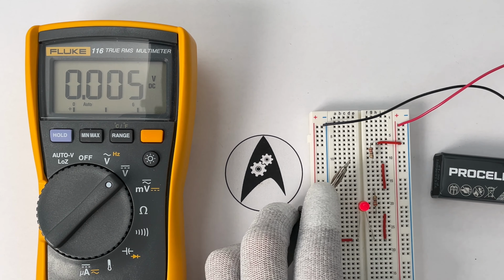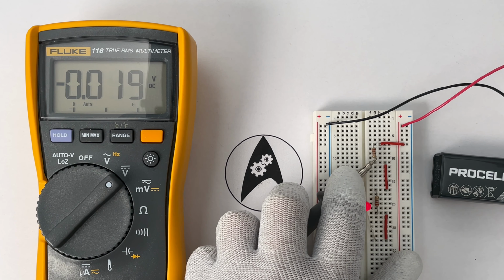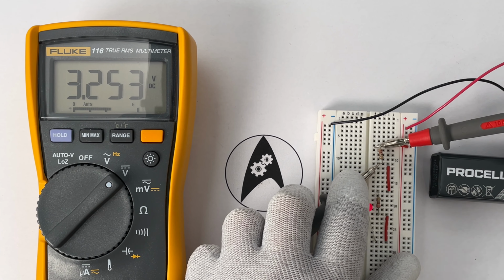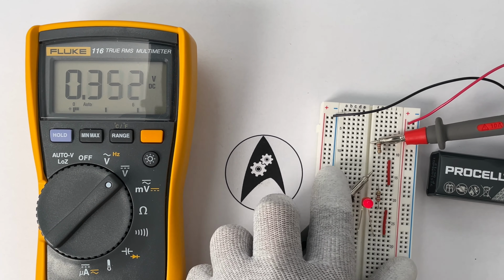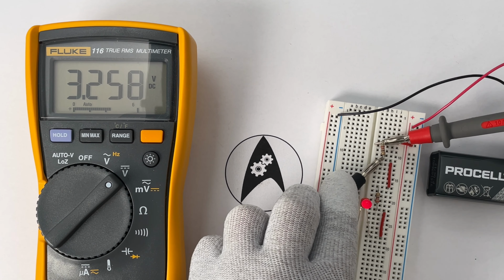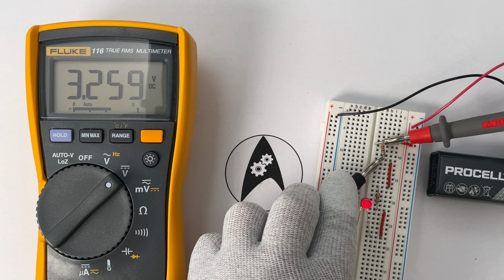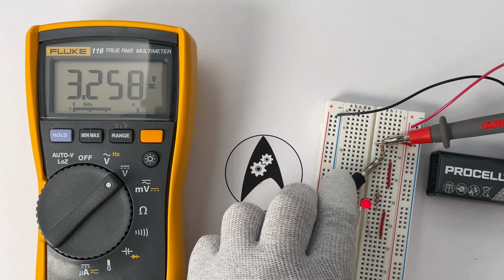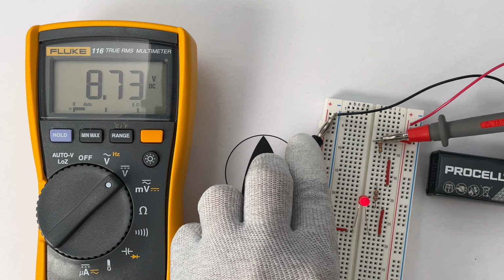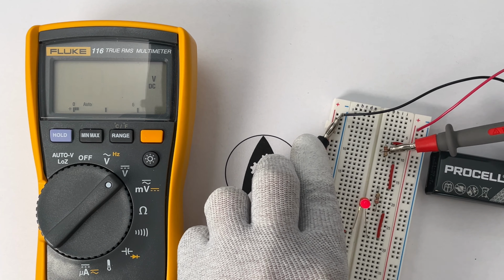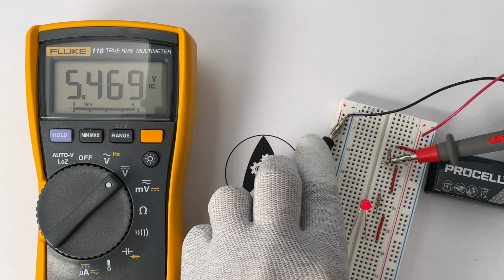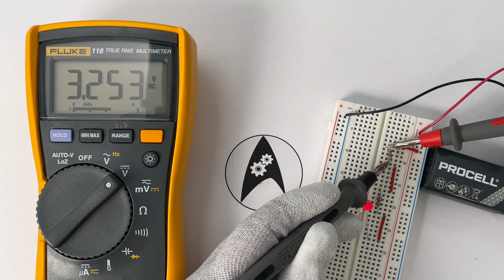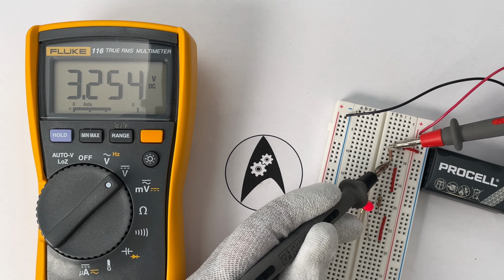Let's put the negative terminal of the measurement tip to the lower part of this resistor here and the positive to the top. Apply a bit of firm pressure here, and you can see, now I've lost connection, and you can see here that the voltage drop across this resistor here is 3.26 volts roughly. So if I again relate it to the negative terminal, you can see it's 8.73 and the lower part is 5.47. You can see that the difference between these two potentials is the voltage drop across this resistor, which is